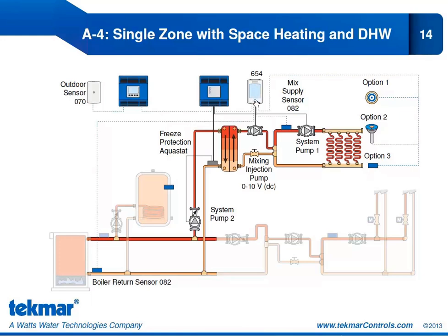So once we configure that terminal to boiler return sensor, it means we can no longer connect an outdoor sensor to the 654. However, since we are connected in the TekmarNet communication to a house control, the outdoor sensor will be connected to the house control, and that information is communicated to the 654 through TekmarNet communication.